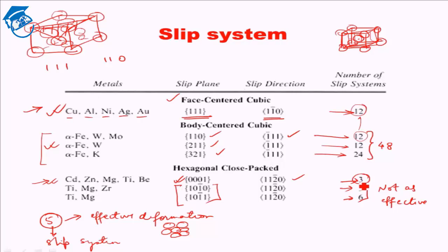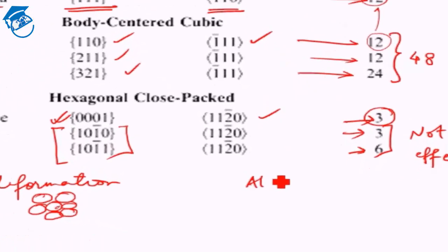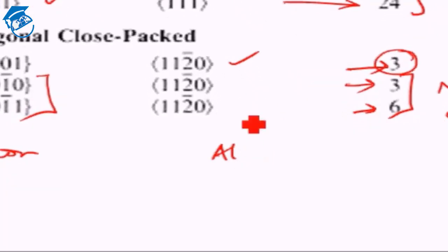So if you read about the details of hexagonal close packed systems, you will see that they are not very malleable or ductile materials, which comes as a great hindrance in, like, the automotive industry. I'll give you an example. The automotive industry mainly uses aluminium alloys now. Aluminium alloys, being the FCC kind, are easily malleable and ductile.